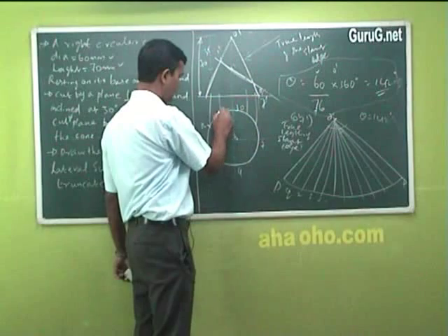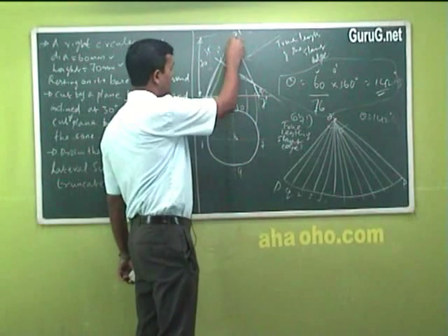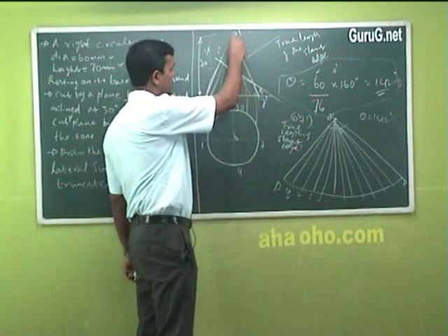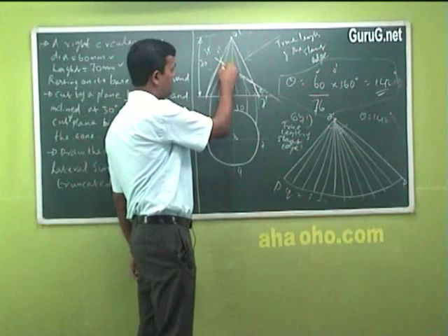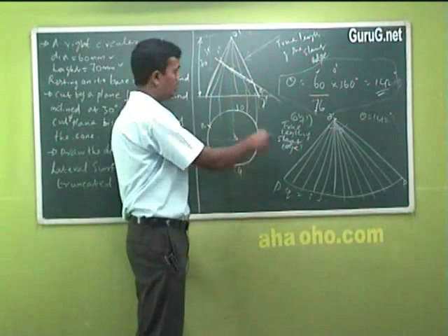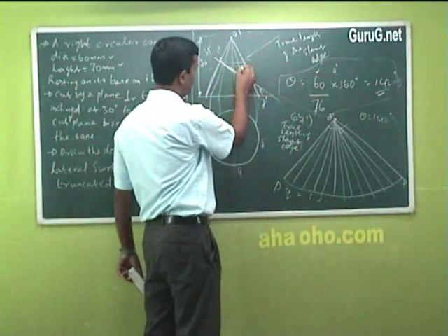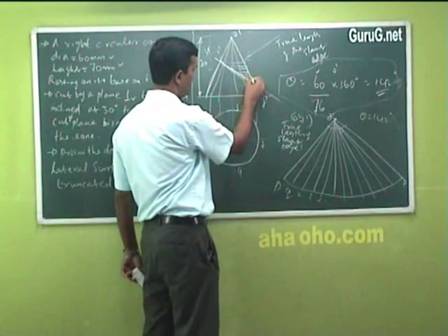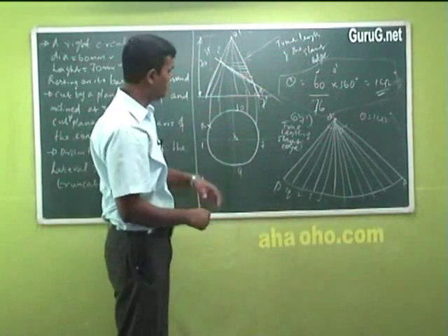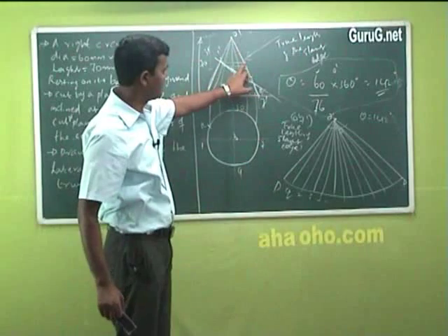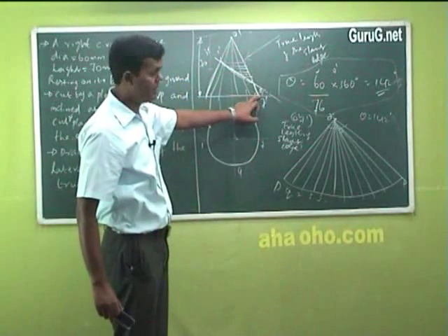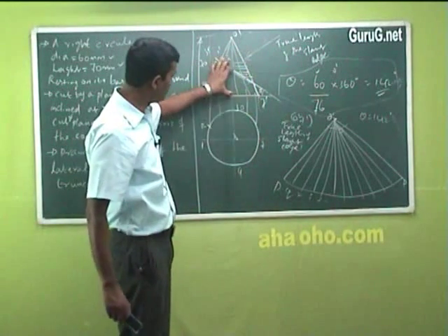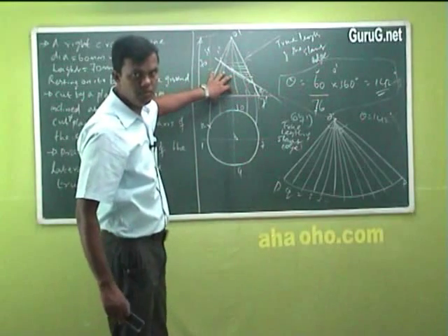You have two points on a curve, so take them as in the previous problems. All the cutting edges lie on different lines. So you extend a horizontal line from each of these points until it touches the true length of the slant edge, because everything is foreshortened in the front view.